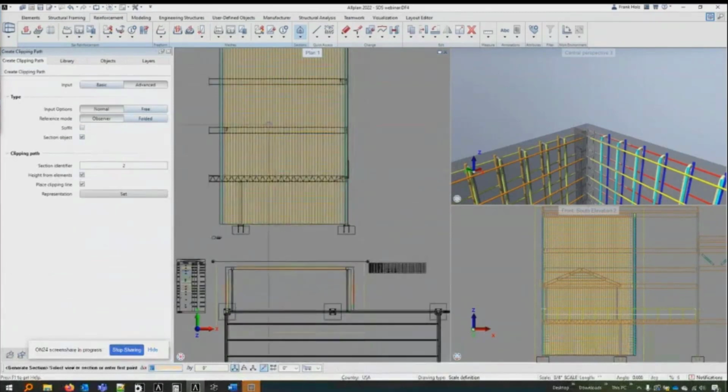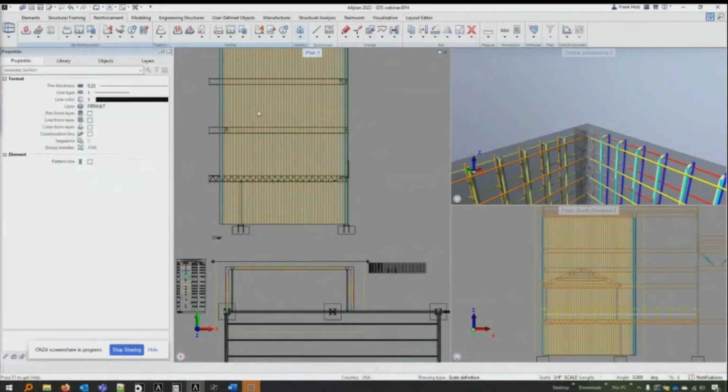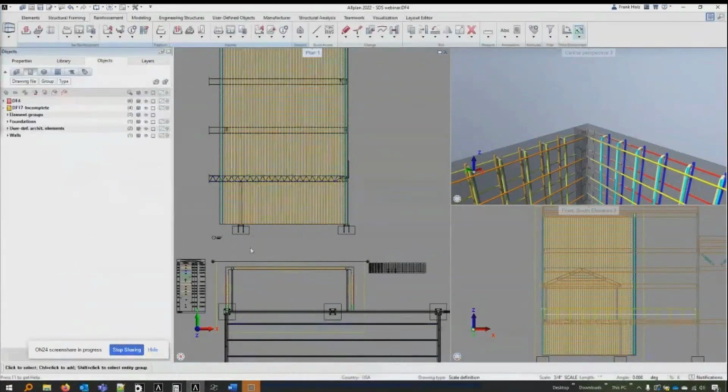I can filter out by layers, by items, by types of things. I can remove individual elements. We'll see more how these 2D sections are fully customizable. They're going to get you 99 to 100% of the way you want in terms of look and feel for your drawings there. All right, so now that I have an elevation view, I can do a number of things here.